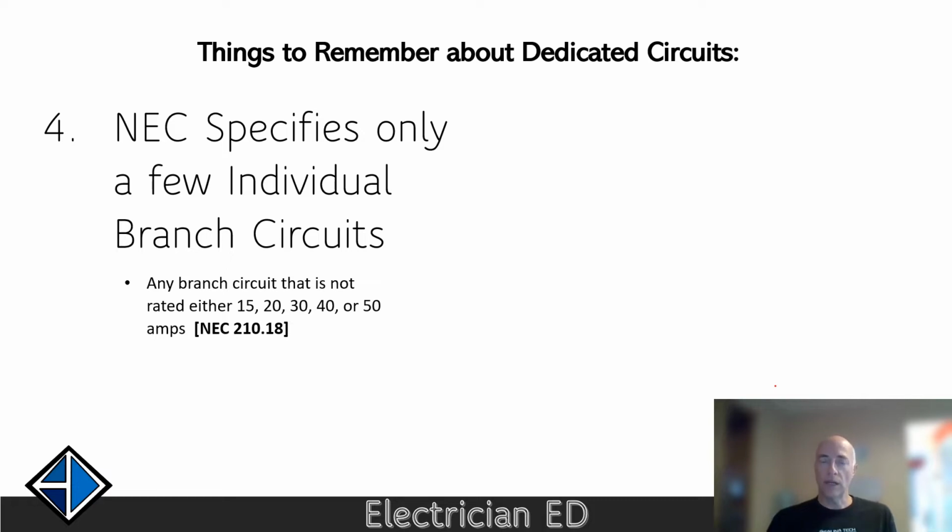Well, you can get a special breaker for that, but that is not in the code book as a standard. So it would have to supply only one piece of equipment. If you see a breaker that has like 45 amps or 35 or something like that, that should technically only supply one piece of equipment.